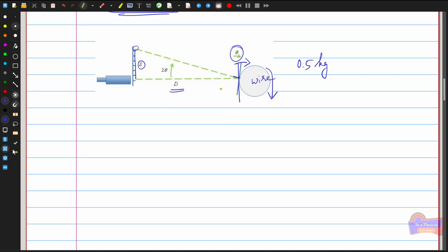Once you have done the readings in one direction, while adding the weights, then the weights are decreased continuously in steps of the same 0.5 kg, and the readings are taken again in the tabular column. So now the torque is reversed. By passing the tape in the anti-clockwise direction, that means in the other direction, again you can take the readings, both the loading as well as unloading. From these readings, the shift of the scale, that is the s, can be calculated for every kilogram.